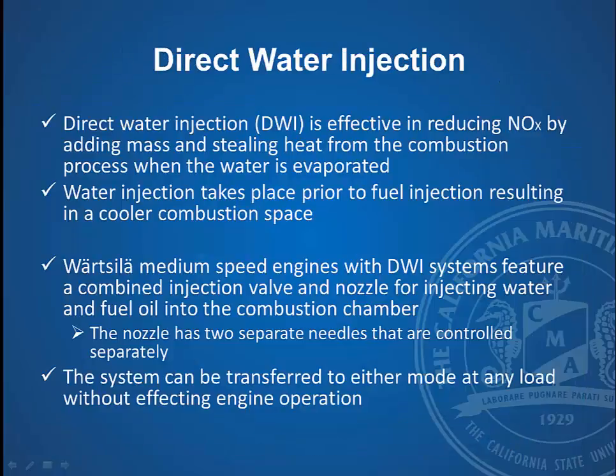Direct water injection is effective in reducing NOx by adding mass and stealing heat from the combustion process when water is evaporating. Water injection takes place prior to fuel injection, resulting in a cooler combustion space. And we're talking about a separate injector, or it can be combined, but it is spraying water directly into the combustion space to cool the combustion air.